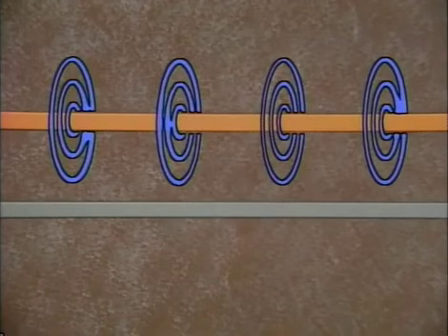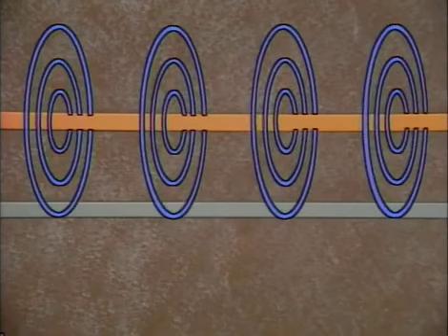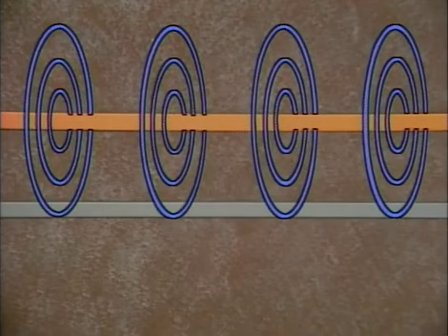Magnetic field coupling can also transfer electrical charges. Magnetic field coupling is the transfer of electrical charges from an energized line to a de-energized line through a magnetic field. Now, this can occur when the magnetic field surrounding a live line crosses a de-energized line. This can induce voltage in the de-energized line and cause the line to become energized.